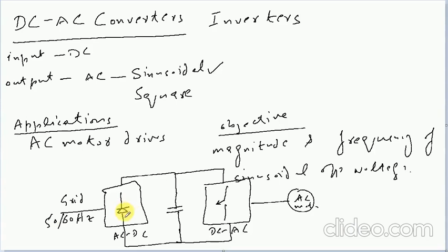Once we have established this intermediate setup, and before feeding this power to the AC motor, we can have that control of the DC voltage, and we can also control the frequency, if that requires a certain adjustment.